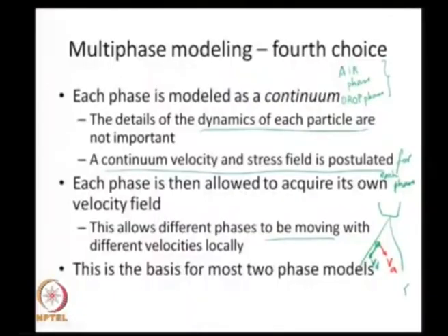The spray is like a jet and the jet entrains air from the outside, and essentially this is like a representative streamline. These representative streamlines mean that the air at this point may want to come in towards the middle of the spray, but the drops may want to go in a slightly different direction.